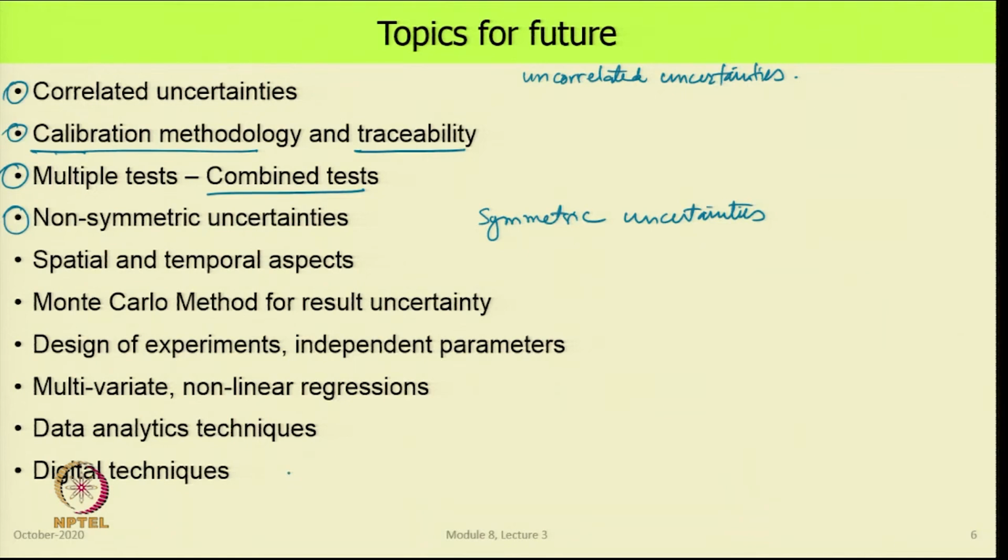In many measurements, there are spatial and temporal aspects and maybe even aspects of the engineering. This we have not gone into detail, and an example of this is if we are using a vane anemometer, which has got blades, a sort of a fan. When air goes through this, it rotates and you count and correlate that with the mean flow through this.